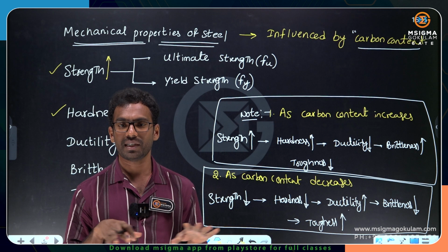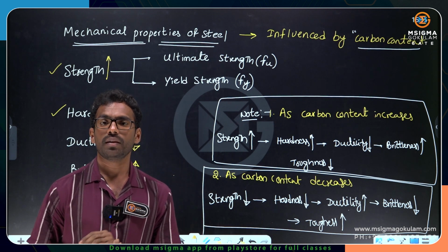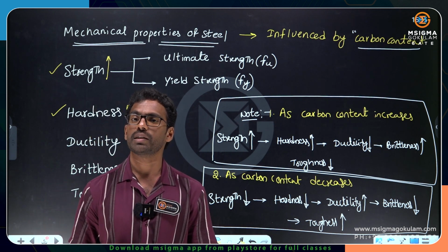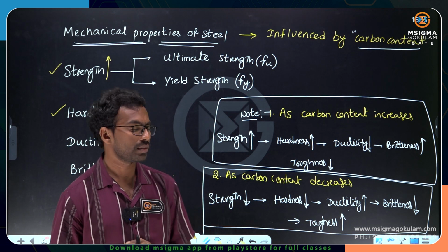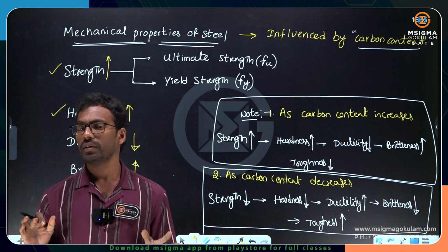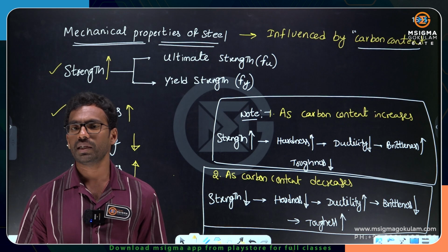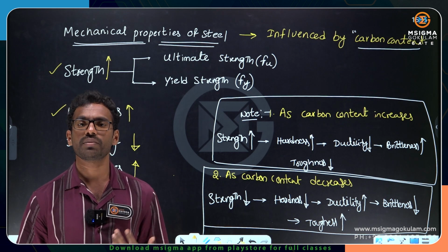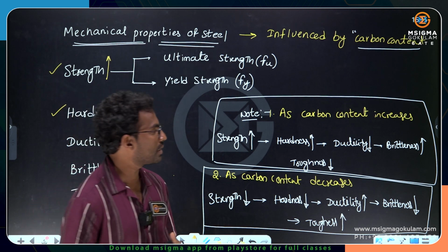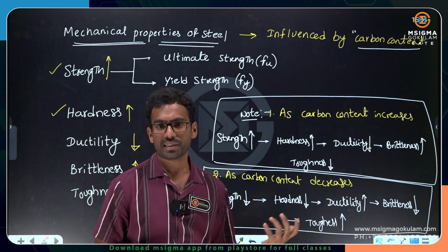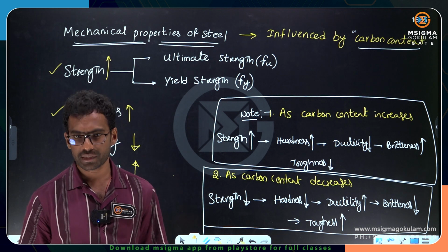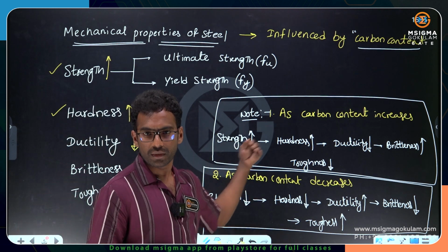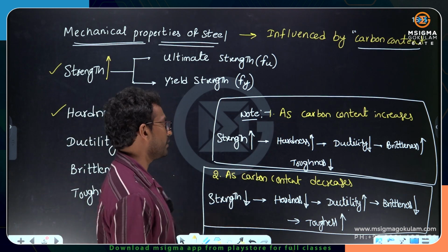So we should have enough ductility, otherwise the system becomes catastrophic and leads to sudden failure. Being civil engineers, we never expect the structure to fail suddenly. It should have some reserve strength before absolute failure. That's why we design all structures by incorporating some factors of safety. We'll see all those things clearly one by one.